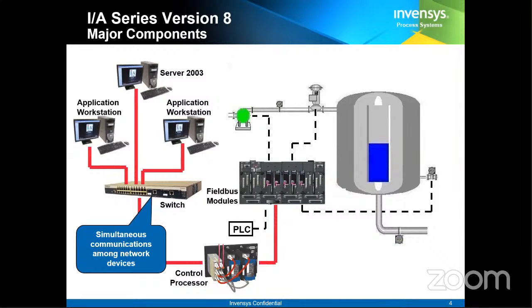If you can see, all of you, in my slide, on the control processor you have two blue color modules. Okay, so they are actually two processors. One is primary, another is secondary. This particular feature is available with most of the DCS systems, and it is a very common feature with the Foxboro DCS system, or with Honeywell or Emerson. So here you have two control processors.